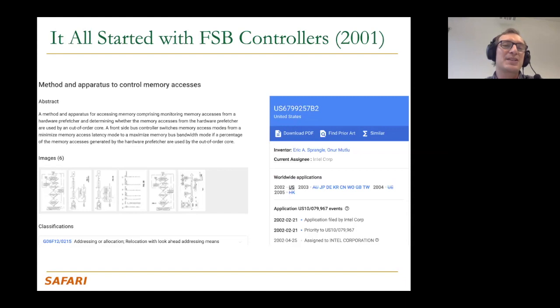So there's a benefit to not integrating the memory controller on chip for both scalability and also being compatible with different types of memory technologies. There's also scalability benefits, because now you can actually expand those chips and have many different memory controller chips. So you can increase your memory capacity by having many of these buffer chips that you can communicate with. And this is actually an approach that's used by IBM in their Power systems.